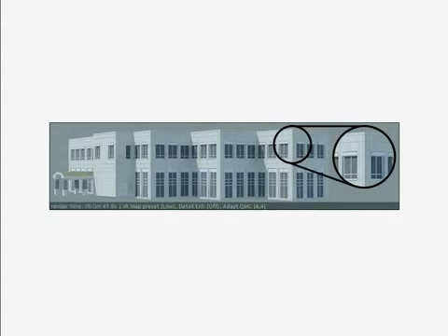More than 75%, I would recommend using the fixed image sampler simply because the small amount of time you're going to save with the QMC sampler is not worth the risk of having certain areas of your scene undersampled. But in either case, you should always experiment to determine which sampler works best for each particular scene.